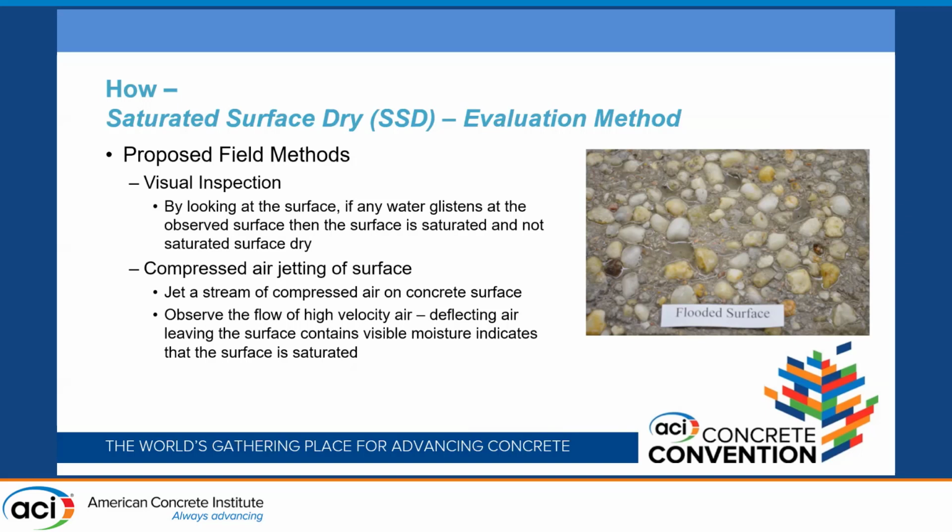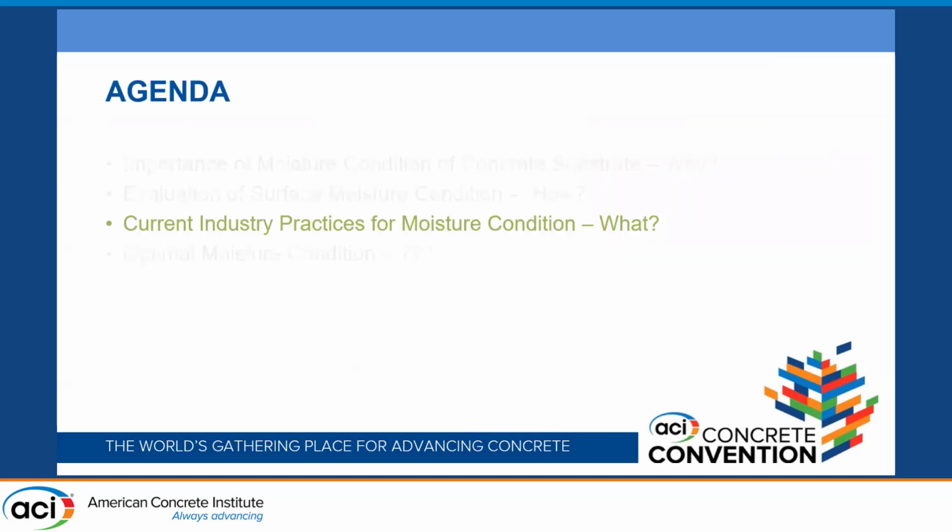When the flow of high velocity air deflects with visible moisture coming to the cardboard, that means the surface is still saturated, not SSD condition. So this is what we know for now about the definition and evaluation of both dry and SSD condition.